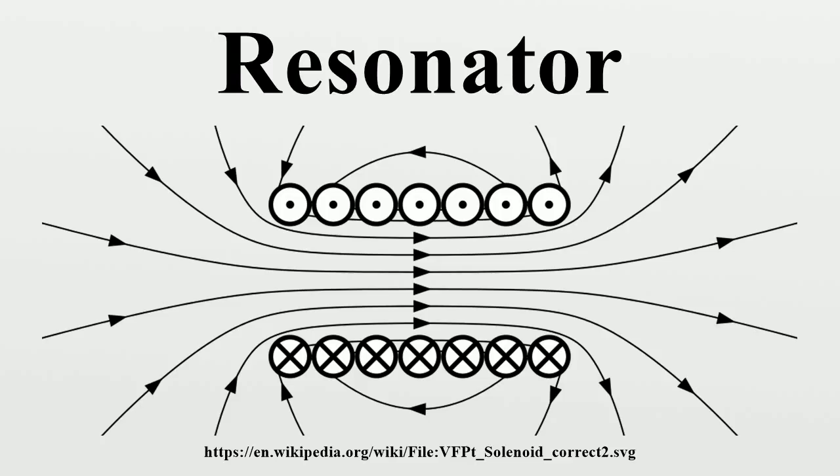The klystron tube waveguide is a beamed tube including at least two apertured cavity resonators. The beam of charged particles passes through the apertures of the resonators, often tunable wave reflection grids, in succession. A collector electrode is provided to intercept the beam after passing through the resonators. The first resonator causes bunching of the particles passing through it. The bunched particles travel in a field-free region where further bunching occurs. Then the bunched particles enter the second resonator, giving up their energy to excite it into oscillations.